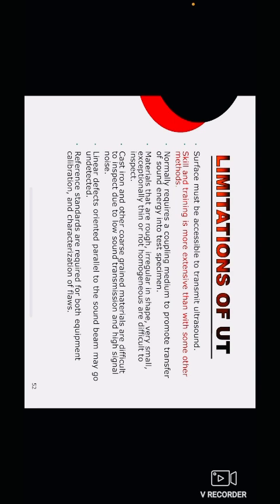There are limitations of ultrasonic testing. The surface must be accessible to transmit ultrasonic sound. Skill and training are more extensive than with some other methods. It normally requires a coupling medium to promote transfer of sound energy into the test specimen.